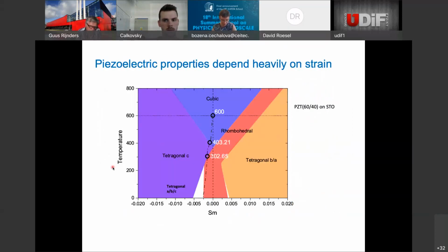And here again, there's a similarity with the talk just before. If you do gallium nitride, for instance, on silicon, because of the difference in thermal expansion, when you cool down the sample from growth temperature to room temperature, you have different thermal expansion, and then you have additional strains inside the film. And that's also true for PZT. So this is a plot from Landau theory where you can see temperature and strain. And we grow typically at 600 degrees, and where the strain is completely relaxed.